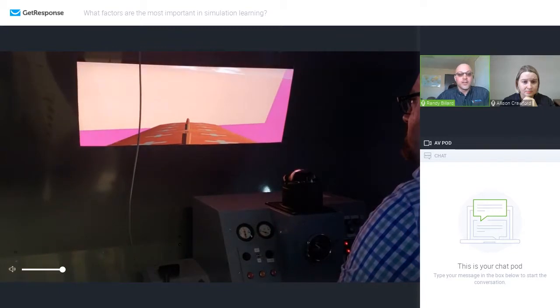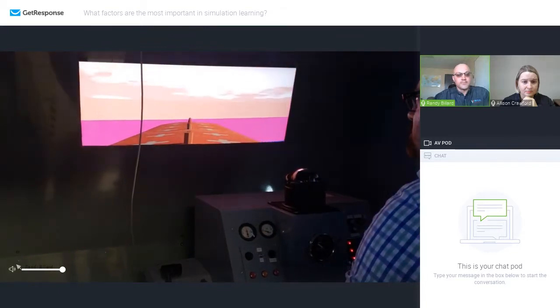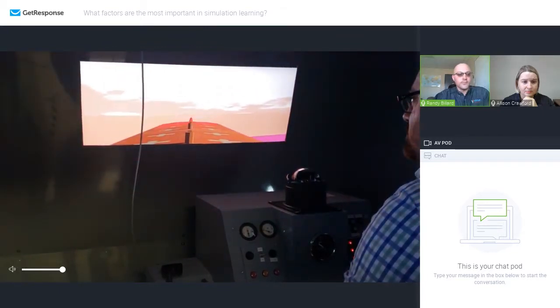And just to let you know, what we found is that there are ways that we can put people through training environments and get them to practice the timing of their release, and to do things that aren't traditionally done in practice, such as running your engine a little bit earlier before entering the water, where people can overcome that backward momentum and get the boat going forward quick enough so they don't make contact with the platform.